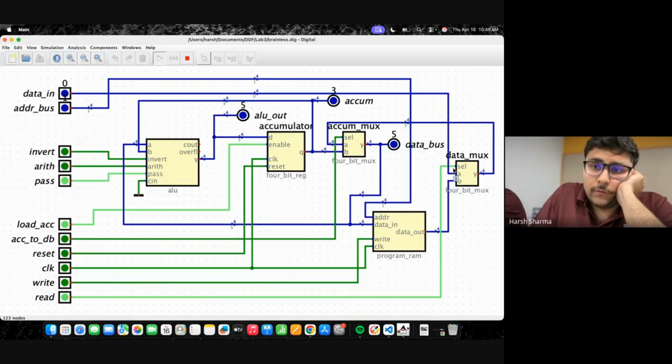5 is going to be, we already have 1. 5 goes back here. We have 0, so 5 goes on to Y. 5 comes to the data bus. 5 goes all the way to A. It's the same as we did earlier. So right now we have B 3 and A 5. Let's close the pass feature since we want to add.